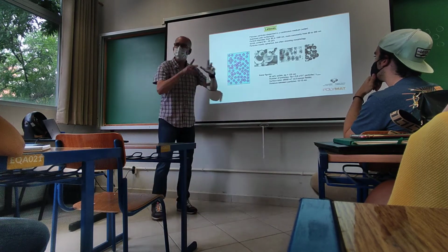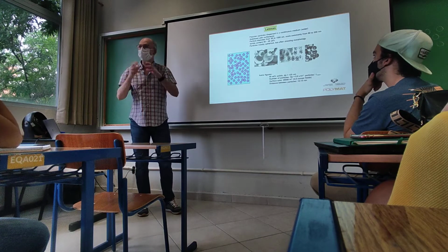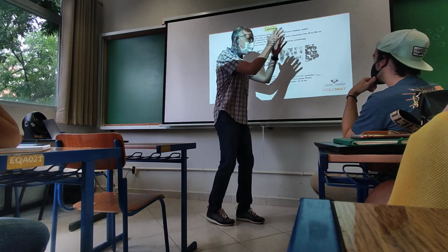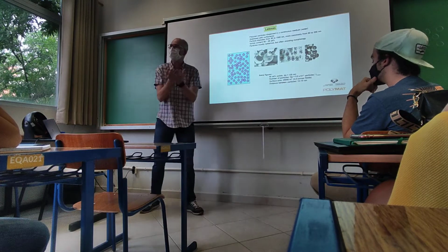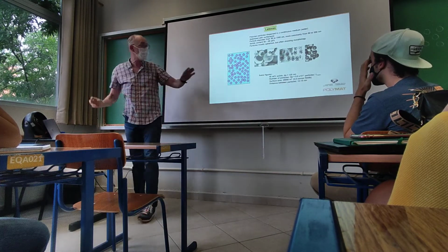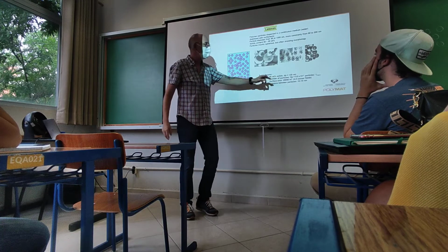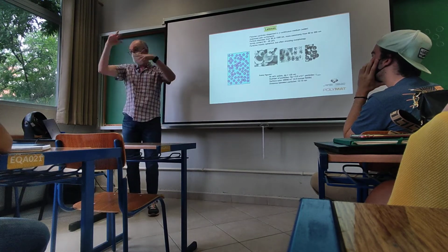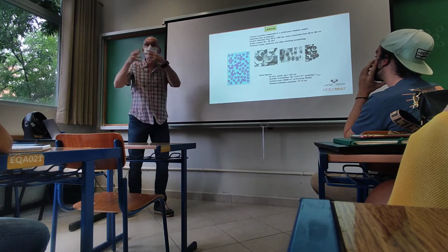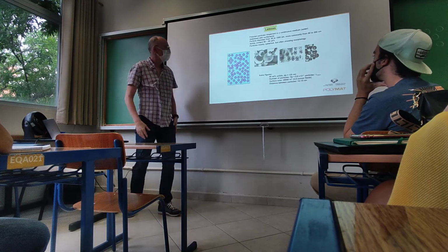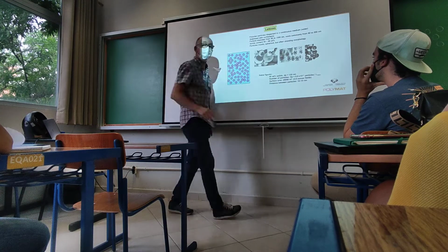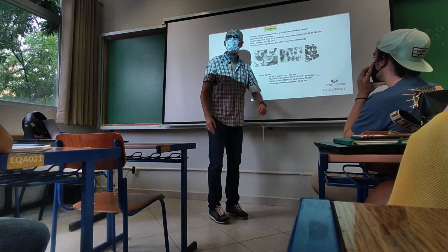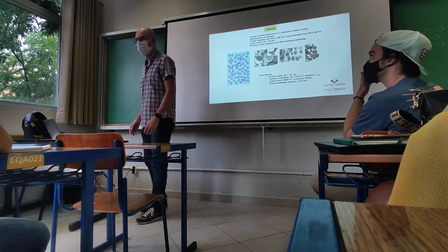Okay, some figures to give you an idea that we are working in the nano world. If we have a dispersion in which half of the dispersion is polymer particles, 50% solids, and the particle size is 120 nanometers, average, because what you obtain is a distribution of sizes. But if this is the average, the number of particles that you have is 5 times 10 to the power of 17 particles per liter.